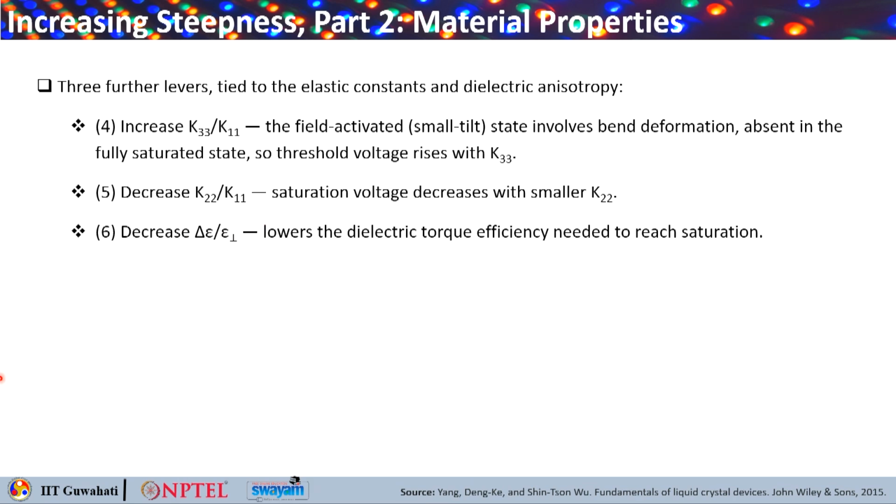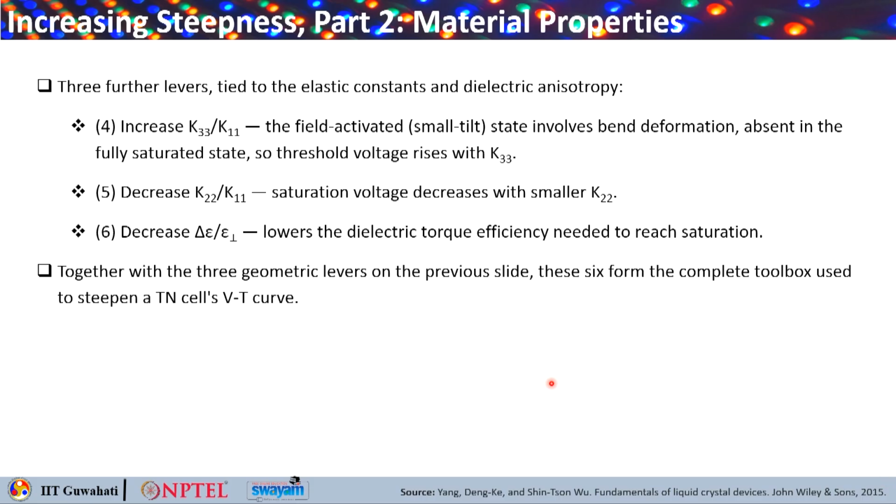And the final one that we have seen here, decreasing this dielectric anisotropy relative to the perpendicular permittivity, that means this delta epsilon over epsilon perpendicular, also helps steepen the curve by reducing the dielectric torque efficiency needed to fully saturate the liquid crystal response.